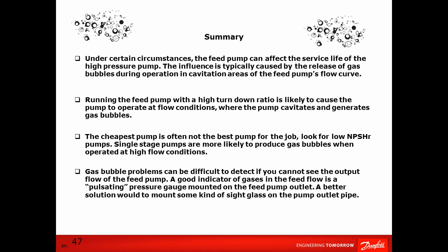If you determine that the high-pressure pumps are damaged by the feed pump water, investigate the operation of the feed pump. If the feed pump runs close to its maximum flow capacity, you are likely to have found the cause of the gas bubbles. In this case, you need to switch the feed pump to a multi-stage pump, preferably with VFD.